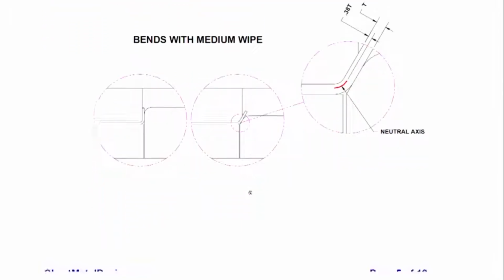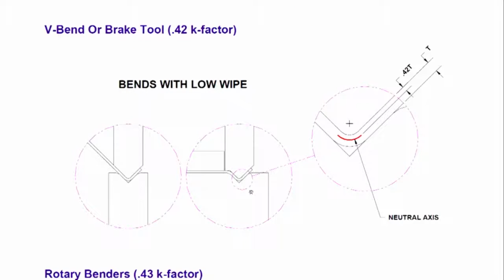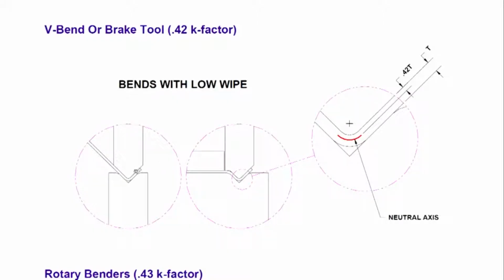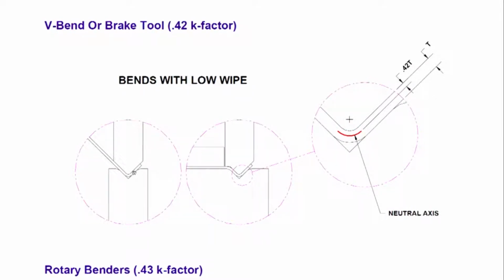So, we have a K factor which keeps modifying all the time. If you have seen the previous lecture, I showed you a folding machine where we have a finger holding it, and after that the bottom die moves up, the bottom limb moves up, and then we have a neat fold. Towards the end, one of the things I showed you was the V brake. So, we have a punch on top, then a die at the bottom, and then you see how the bend takes place here.